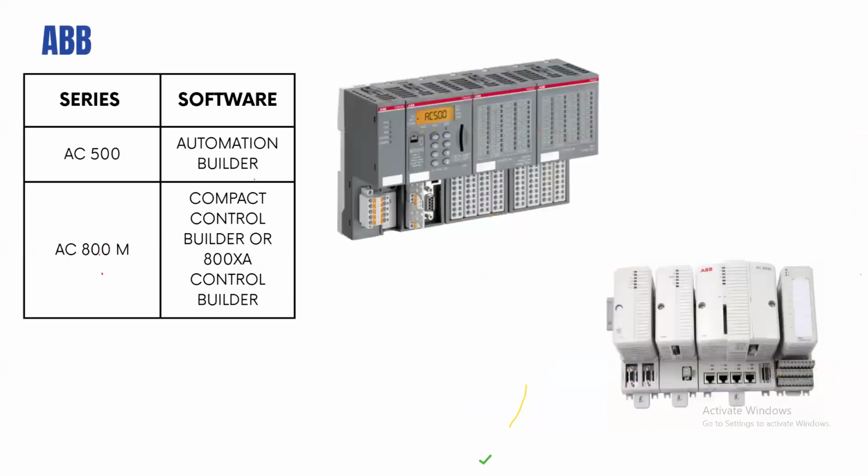So we have ABB as well. We have the AC500, which uses Automation Builder and is used for very small automation systems. Then we have the AC800M, which, depending on whether you're using it as a PLC or a DCS controller, uses something called the Compact Control Builder or the 800xA Control Builder Professional.